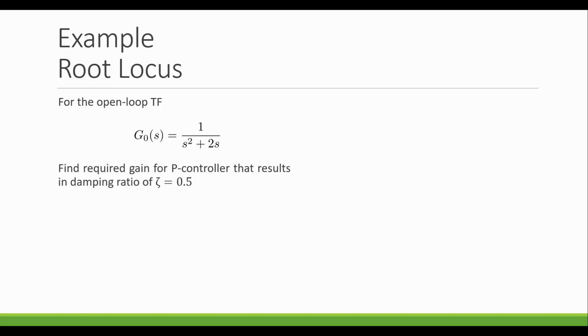Those are going to come from what we desire for maybe the peak time and the max overshoot as two examples, but we're usually going to select those first, and then from the selection of those values, select the natural frequency and damping ratio. So now we can look at all of the different gains that we could choose for this P controller system and see how it's going to affect the pole placement, and then the poles are going to affect the damping ratio and natural frequency. In this example, we're not going to be concerned about natural frequency, just the damping ratio.